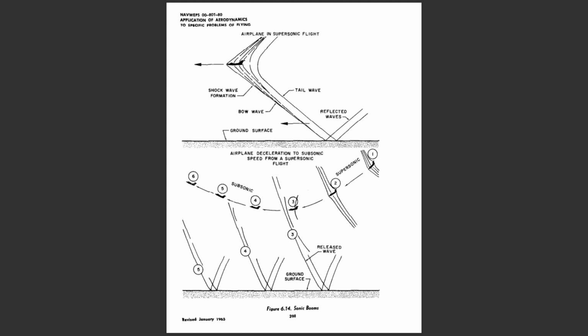The damage potential of the ordinary sonic boom is quite small, and the principal effects are confined to structures which are extremely brittle, low strength, and have characteristic high residual stresses. In other words, only the extremes of pressure waves generated by airplanes in flight could possibly cause cracked plaster and window glass. Such materials are quite prone to sharp dynamic stresses, and when superimposed on the high residual stresses common to the products and building construction, slight but insignificant damage may result. Actually, the most objectionable feature of the sonic boom is the audibility, and the anxiety or apprehension caused by the sharp, loud noise which resembles a blast.